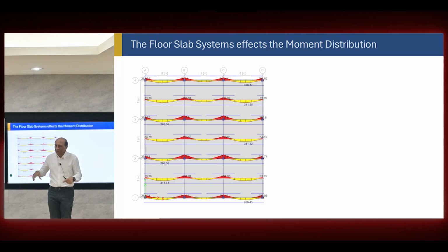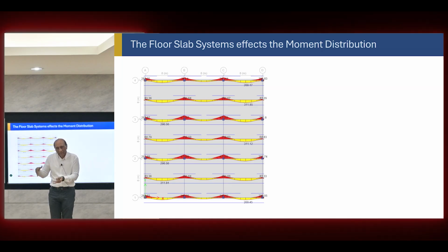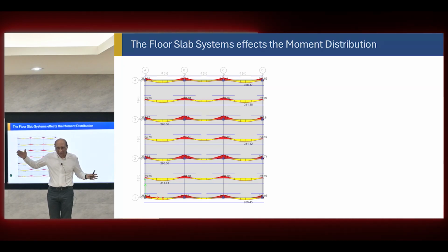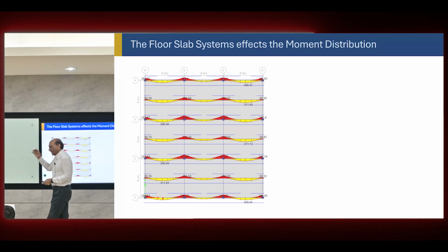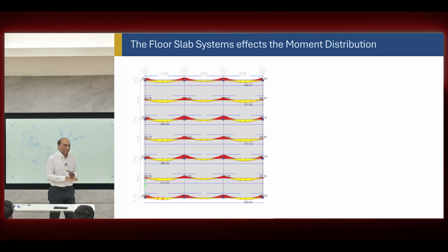If there's a beam, no reinforcement there or very little reinforcement there. So you go back to the two-way slab concept where more reinforcement in the middle, less on the column. If there is no beam, more reinforcement on the column, less in the middle. So the entire transition between a flat slab system and a pure beam slab system is now consistently uniform.